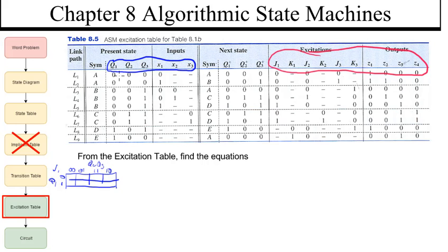All right. What's J's value here when they're all zeros? Well, when both rows are 0, then we don't care about these inputs, and J1's going to be a 0. So I'll put a 0 right there. Now let's look at all three of these rows. Is J all the same? No. But it looks like it's whatever the value of x1 is.